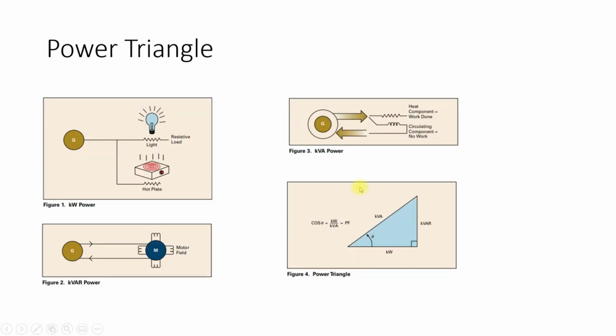So how do we represent this power? We use the term apparent power, or kVA. That's why you have seen that these motors, generators, and transformers all have their power in MVA or kVA, basically apparent power. It's not in megawatts. The reason is that each of this equipment has some inductive load associated with it. So when the power flows through them,